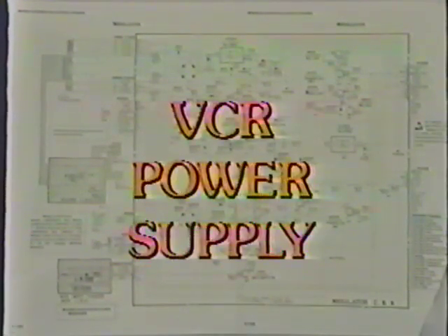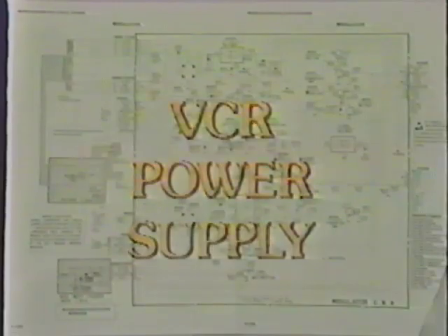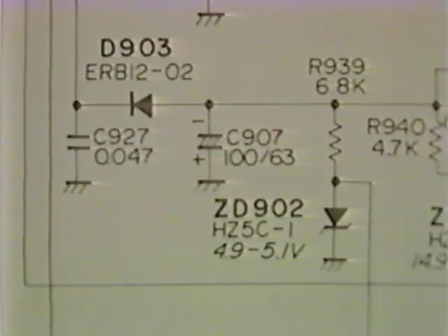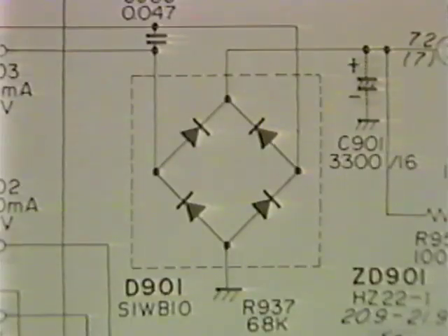Because its circuits need a variety of voltages and currents, a typical power supply in a television, VCR, or other consumer product may include all of the rectifier, filter, and regulator circuits discussed. A low-current circuit may be powered by a half-wave rectifier with a single capacitor filter and a simple Zener regulator.